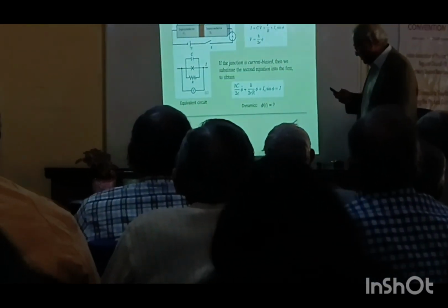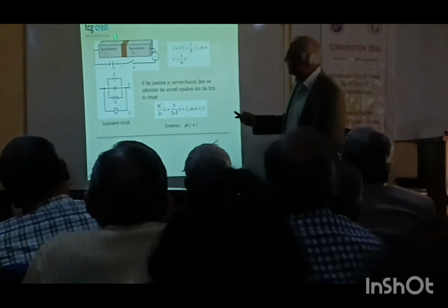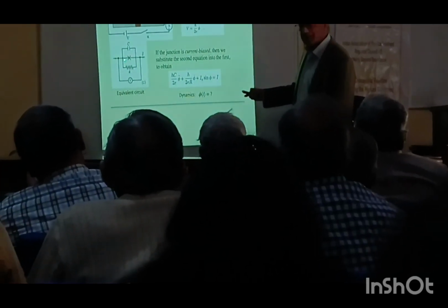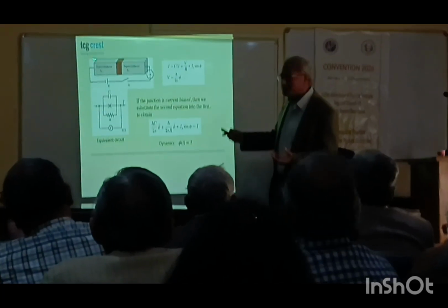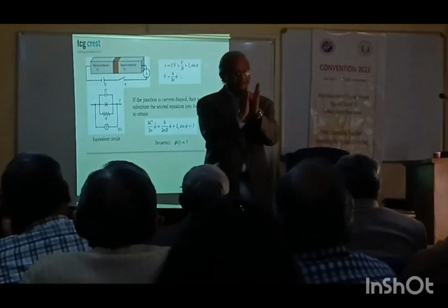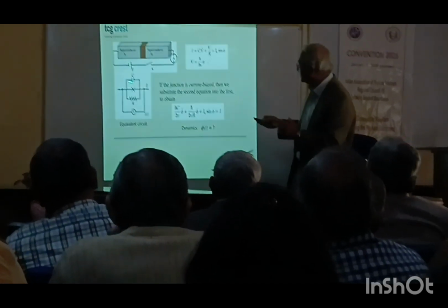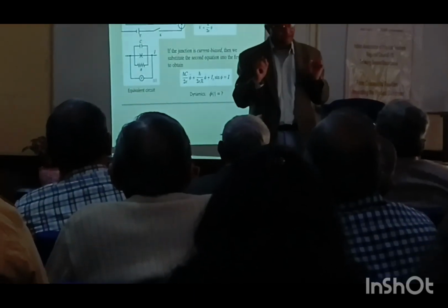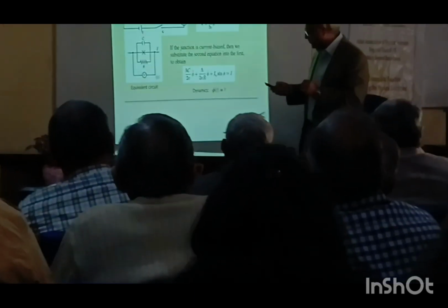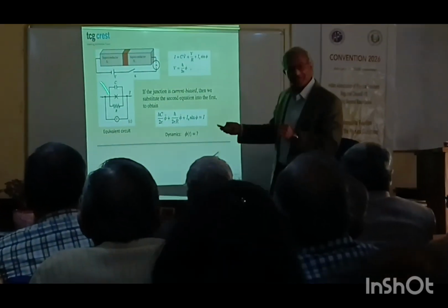So now I go back to the same circuit. Now if you want to make a diagram for the electric equivalent circuit, this is my Josephson junction here. And since these are two pieces of metal, which are superconductor, but this is an insulator, an insulator between two pieces of metal is a capacitor, right? So there is a parallel effective capacitor here. But since this is an insulator, it may have some resistance. So I put that parallel resistance here also. Now I pass a current through this. So this is my equivalent circuit.